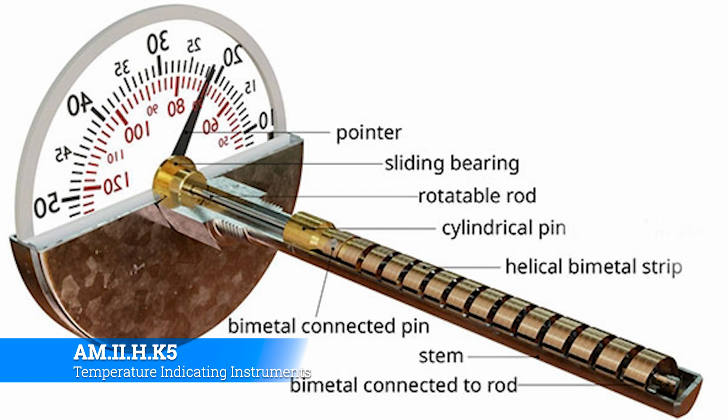Essentially, you have two metal strips in there, and as the temperature changes, the expansion and contraction of those metals also change. As they physically move because of that change, it moves the needle one way or the other. And since we can mathematically work out exactly those rates of expansion, we can say, hey, at 100 degrees, they should be in this configuration. So we put a little pointer on it, and we say that's 100 degrees. We say, hey, at 50 degrees, they should be at this configuration.